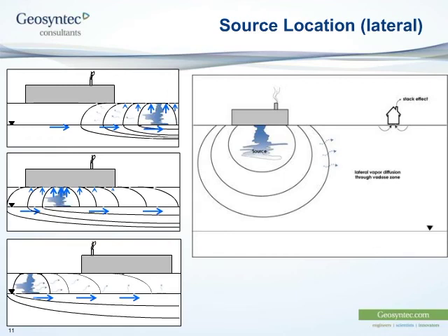Chemicals can also migrate considerable distances through the unsaturated zone, especially where the vadose zone is thick, and this occurs more often in arid climates, and I know there are certainly portions of Australia that are very arid climates. So you may have a deep water table, and off-gassing from groundwater may not be a threat if it's deep enough, but lateral migration through the vadose zone can be a concern. It should not be ignored. Generally, concentrations of concern could extend up to 100 meters or more from a source area, but usually not much further than that.